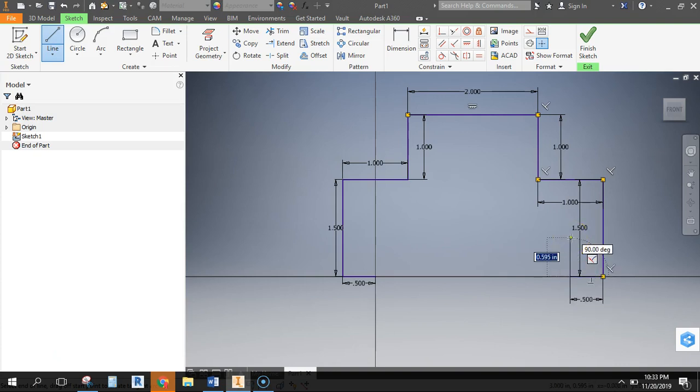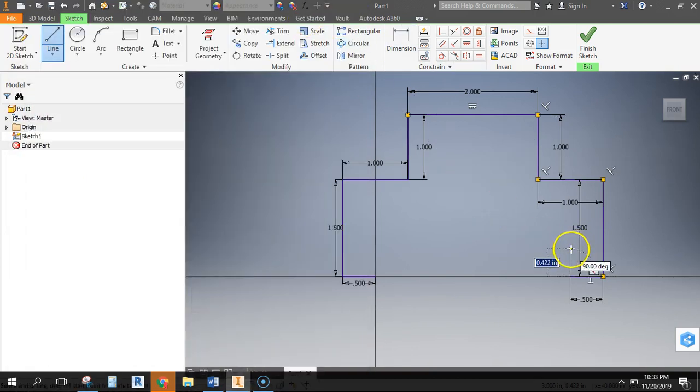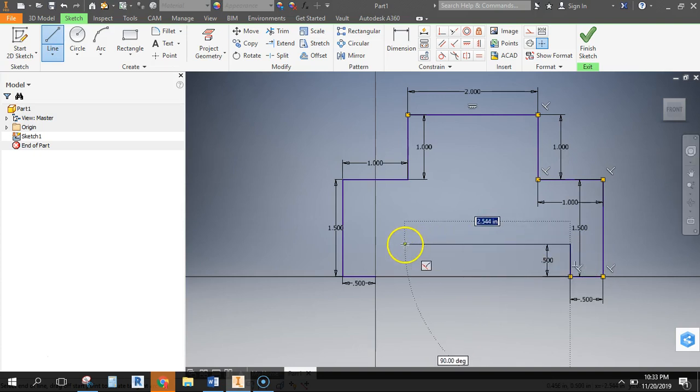Then go up. I've got to look at that measurement. That measurement is this one right here. And it looks like there's our indication of how big it is. So it's 1/2 inch. So I'm going to go up 1/2 inch. .5, hit enter. Over. This one is 3 inches. Hit enter. And then down 1/2 inch. And hit enter.